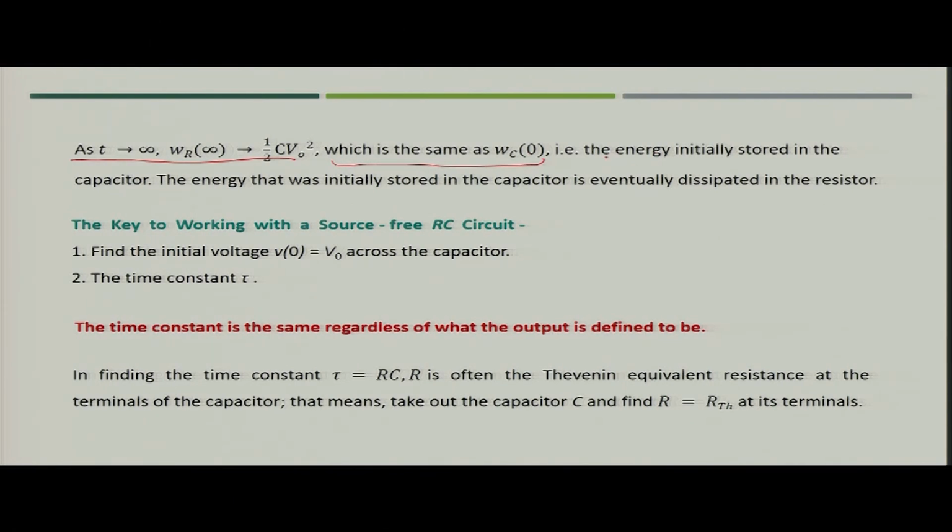So, we will say that the total energy which was there in the capacitor is discharged in the resistor in time that is infinity. So, it will take infinitely longer time to finally dissipate completely the energy which is available in the capacitor. Now, there are two important points to remember when we work on the source free RC circuit.